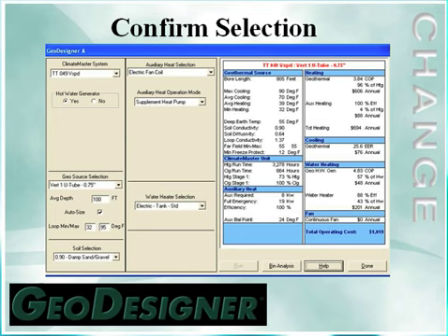One thing I do want to point out, if we're selecting the unit on the cooling load being our dominant load, in the bottom left portion of this screen, underneath where it says auxiliary heat, we would have a screen come up if the unit that we selected is undersized. It will tell us total cooling we can't meet or sensible cooling can't meet, and we would simply select the next larger unit to make sure that we're covering our cooling requirement.